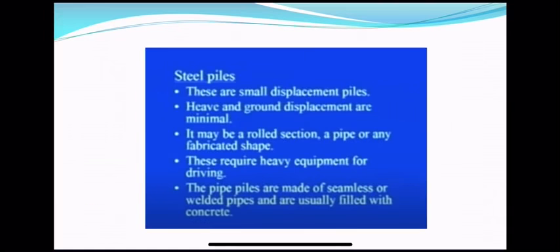These require heavy equipment for driving because their weight is very high, and they are precast; we just cannot cast them at the site. Why you require heavy equipment for them is that the piles are made of seamless or welded pipes and are usually filled with concrete.